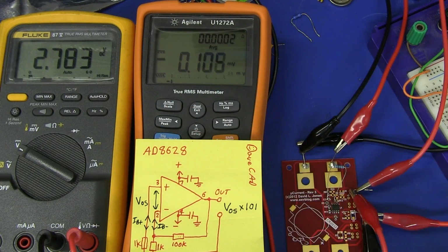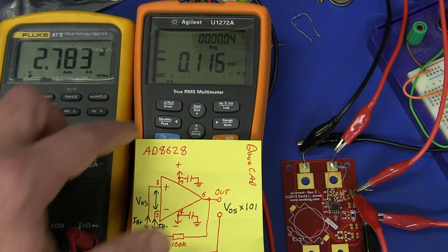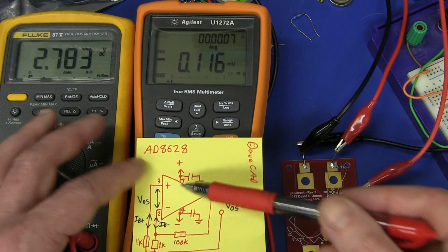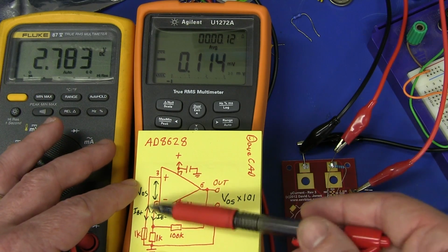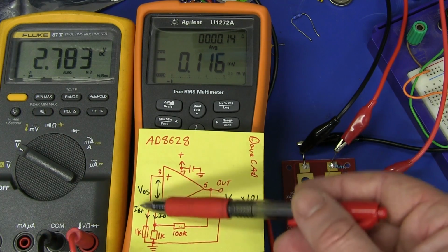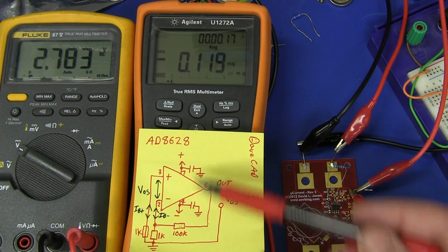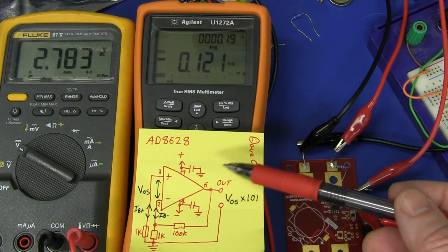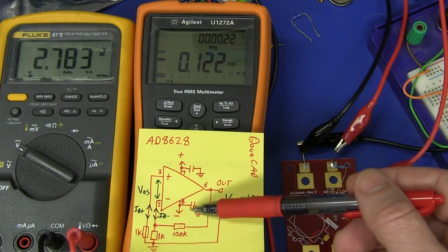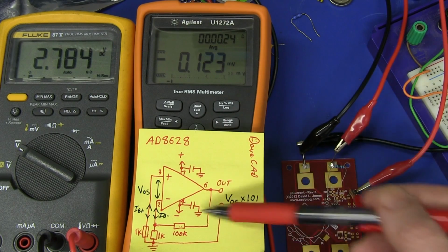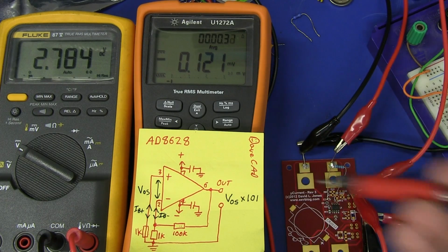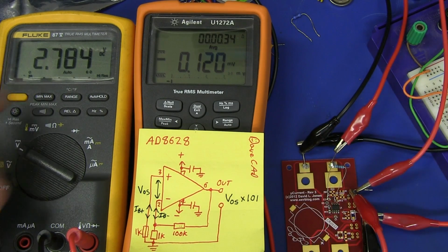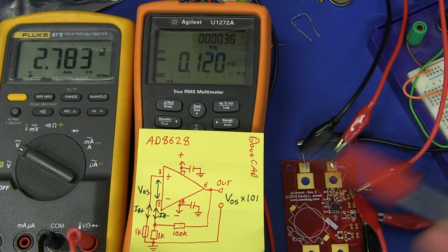There we go. Average. We've gone all the way from positive to negative there, because this is a rail-to-rail op-amp. As I said, the topology we've got allows currents to flow either way, and in combination with V offset, which also could change over the supply rail range. So the common mode range is different, and our bypass decoupling as well, which we saw made a difference in the previous video. All these things combined make this a tricky circuit to actually null out completely over the supply range, but I'm pretty happy with that.